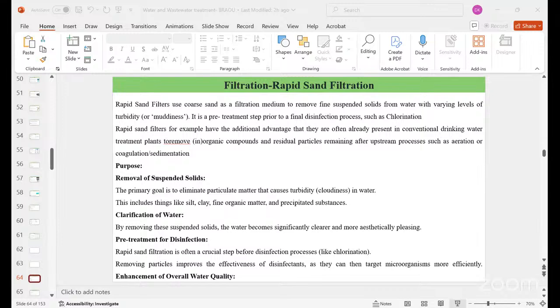And backwashing, which is another factor that keeps the filtration going easily, and it also prevents the filter bed from becoming clogged. So there is biofilm formation biologically, or a formation of clogging materials on top of the bed, and through the process of backwashing, the filter bed is washed such that the pores do not get clogged, and sediments can easily pass through the filter media.